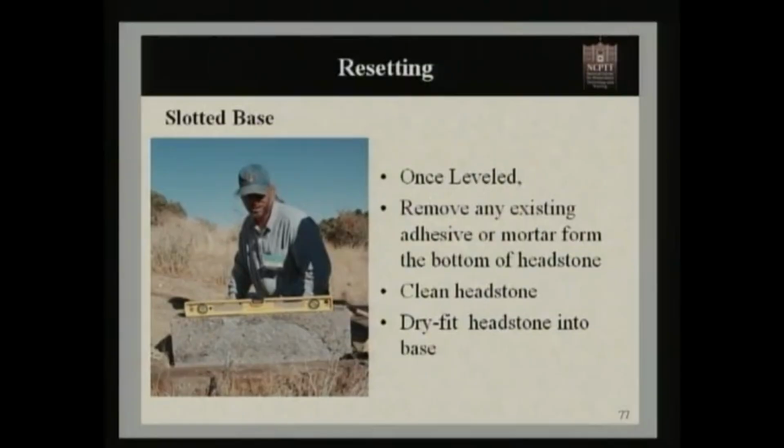The next thing we want to do, once we've leveled this, is remove any existing adhesive and mortar from the bottom of the headstone. Just like in our base, a lot of times on the bottom of the headstone we have these left. And this is a really good time to clean the headstone. Wash the base and the headstone, like we talked about earlier. Remove all this failed material. And then a very, very important step that a lot of times gets overlooked is we want to dry fit that headstone into the base before we move further. We want to make sure that that headstone fits properly into that base before we apply a new mortar or a new adhesive.